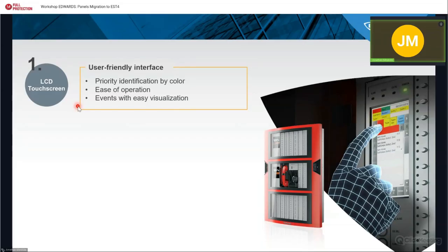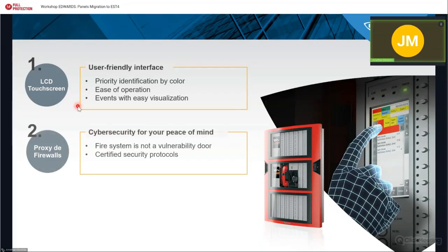You will see everything in a tree structure. Remember, everything in the EST4 is a tree structure. If your building has 10 floors, 20 floors, you will have to program your database in a tree structure. Then you will have the cybersecurity. As I told you, the fire system is not a vulnerability door. You will have certified security protocols with our firewalls within the EST4.